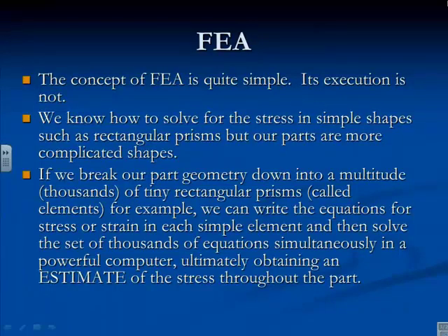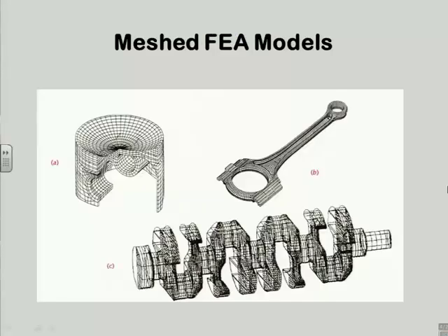Well, it's an element, and there is a finite number of them, though it's a large finite number, that's the name. And since we know how to calculate the stresses and deflections and all that stuff of a rectangular thing, we simply solve a lot of simultaneous equations to find it for all of these little bricks at once. That's essentially the basis on which FEA works.